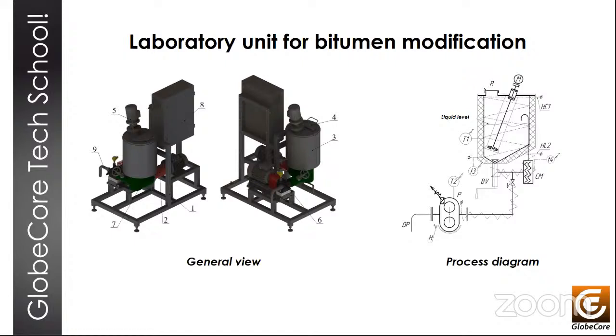So looking at the flow diagram, let's look at the operation of the machine real quick. First, the operator checks the position of the valve V and the bottom valve BV. They all must be completely closed. Then the operator starts the heating process. The control system can hold temperatures within specified limits, for example, 160 to 180 degrees.